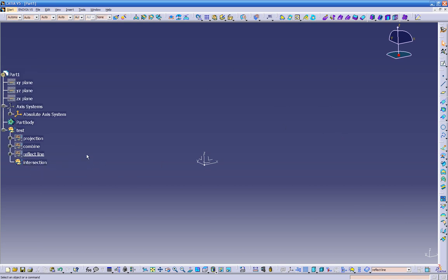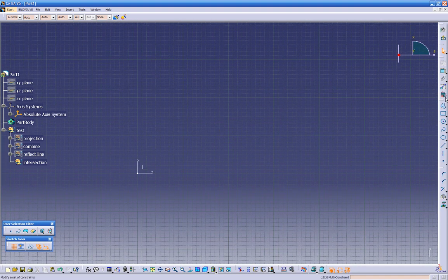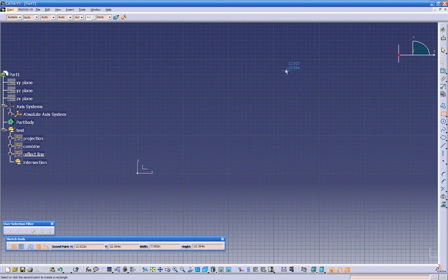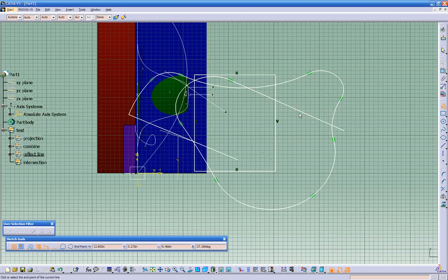Let's make this the default, because right now if we try to build a sketch, for example, and we try to make a rectangle, we don't see it, right? We try to create a profile and we can't see it. It's like, what's going on? The reason we can't see it is because this is the default and it's already turned off. So right now everything that we're building goes into this folder at the no show level. So if I go to swap visible space, there we go. This is all what I'm creating right now. Because this is turned off, everything that I'm working on right now goes into this level.